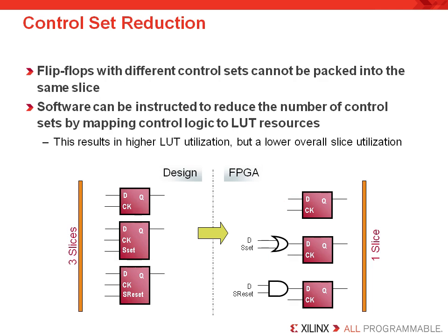As I mentioned, flip-flops with different control sets cannot be packed into the same slice. So in this example, we see 3 flip-flops resynthesized to force some control signals to associated LUT inputs so that these registers can be packed into the same slice. Now this is accomplished by using XST's control set reduction option. Hopefully in the near future, all synthesis tools will incorporate this functionality automatically on every design.